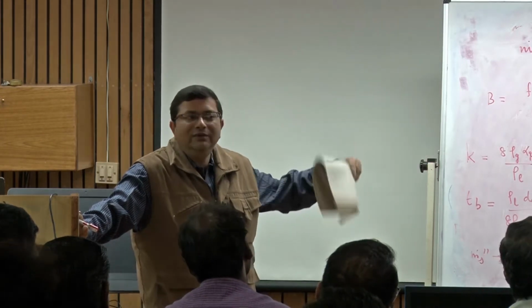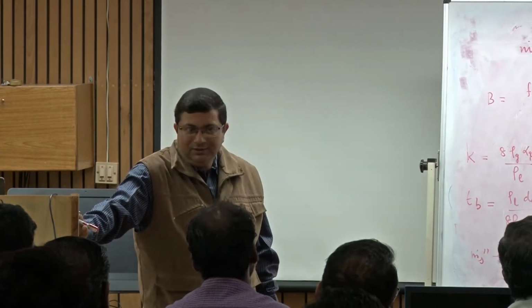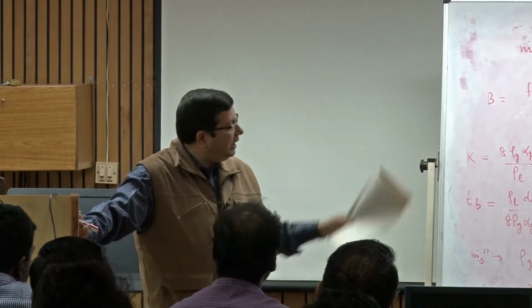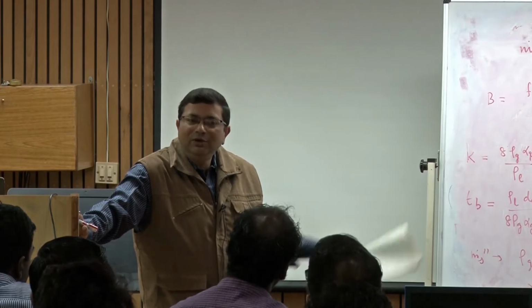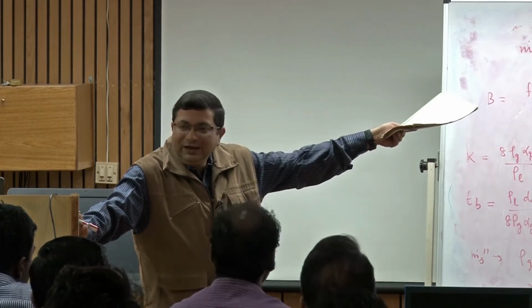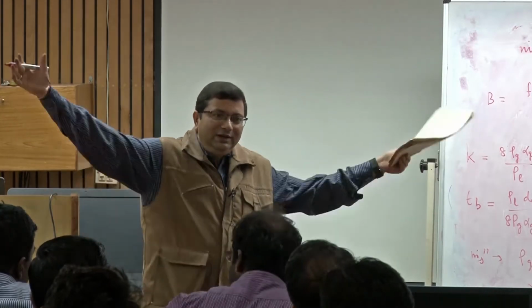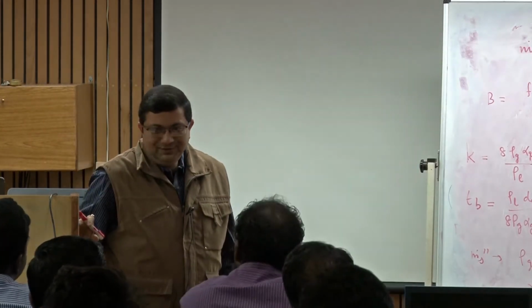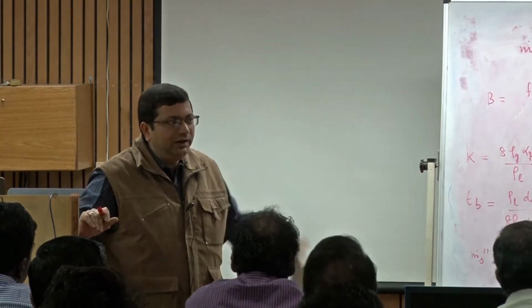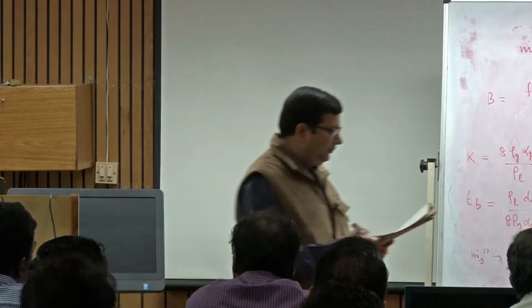Alcohol has a much lower heating value compared to aviation turbine fuel. So, even though we know that the combustion characteristics will be good, for aircraft application we do not burn alcohol, because the combustion rate will be so slow that you will require a much longer combustor, which will increase the weight. So, you can see from here we need to have a large heating value; alcohol has a lower heating value compared to the fuels.